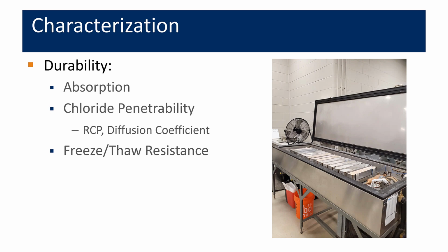which a lot of DOTs specify, or it can be accomplished through a diffusion coefficient test, which is probably a little bit more accurate for a material like this that's got a pretty high density. And finally, you can characterize the freeze-thaw resistance, which I'm showing in this figure here.